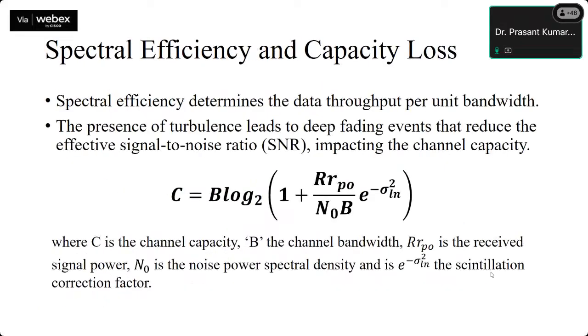And as I said, one of the other requirements. Next one is communication, the spectral efficiency and the capacity. So the spectral efficiency basically defines how closely we can pack the information such that we can improve the bits per second per hertz capacity. In other words, how do you increase the throughput, that is the transmission rates.